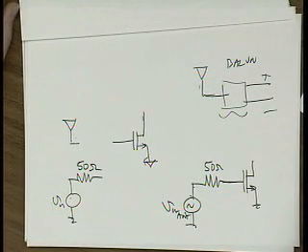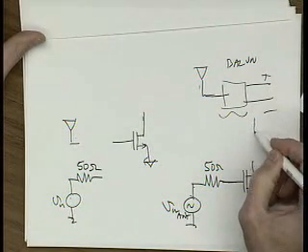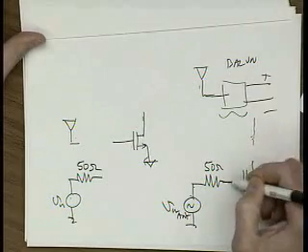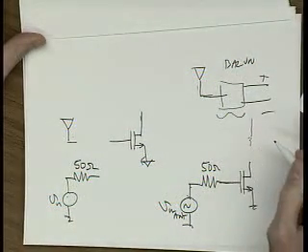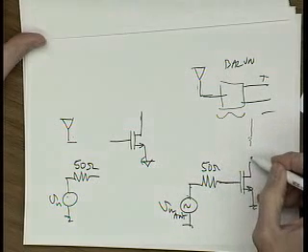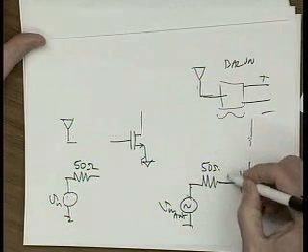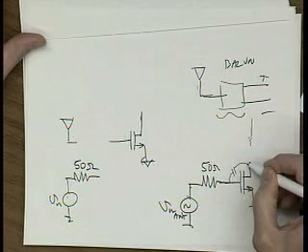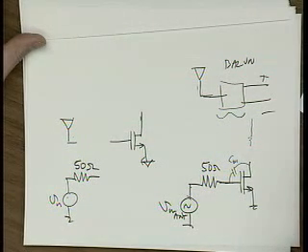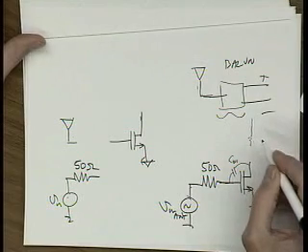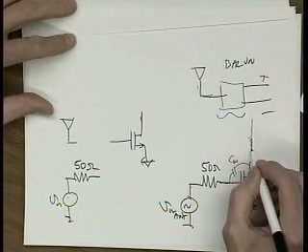What? A resistor? What about Miller multiplication effects? Don't we have a problem here? If we go right to a load right here, don't we see a CGD here that gets Miller multiplied by this gain? So what do I do? Cascode it, right? I should cascode this thing, right?